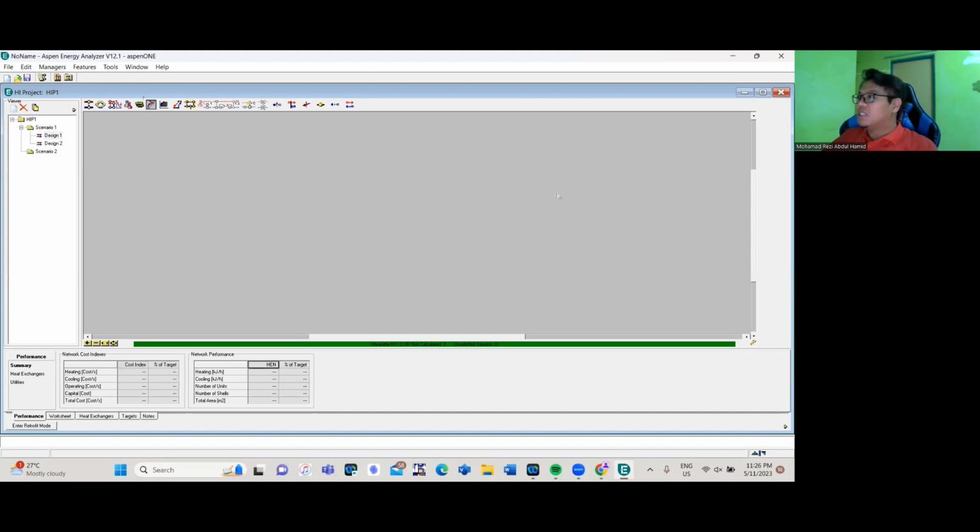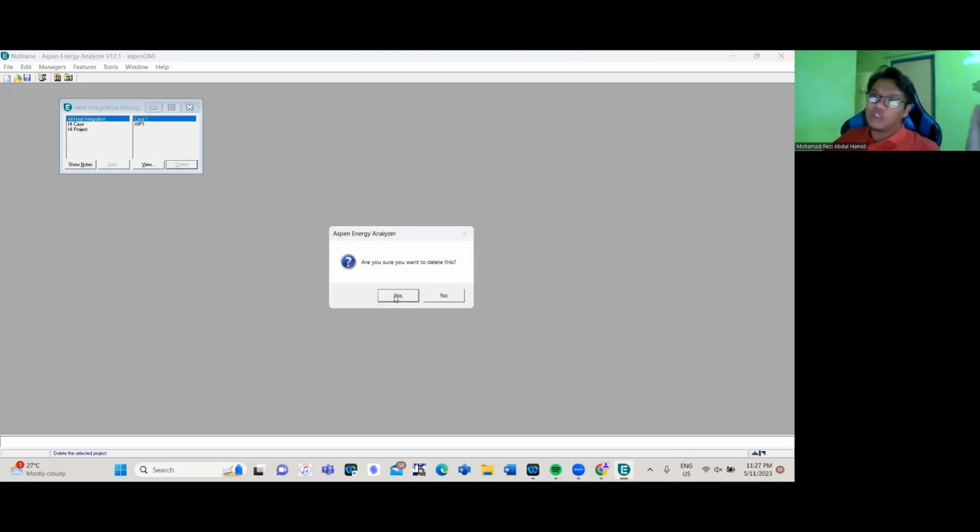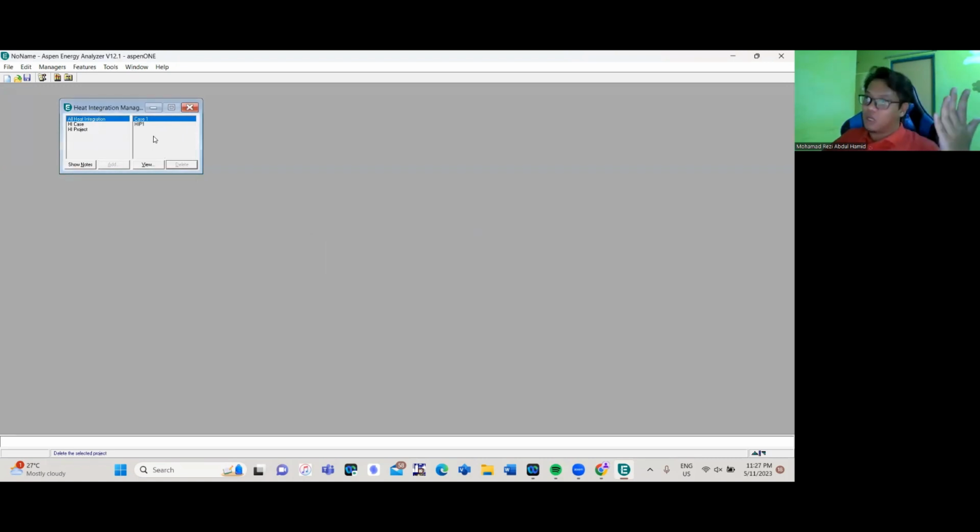All right, I'm going to close this. So if you see heat integration manager here, let's say I close this one first. If you go to heat integration, click the manager, click heat integration manager. Right now under heat integration project, you have one project because we already added one, and under heat integration case, you have case one because you added one just now. All heat integration is basically displaying all the cases as well as projects. Of course, this is like a file or a scenario which you can delete. Just click delete, and it's going to ask you whether you are sure to delete or not. So click yes if you would like to delete, click no if you decide not to delete.